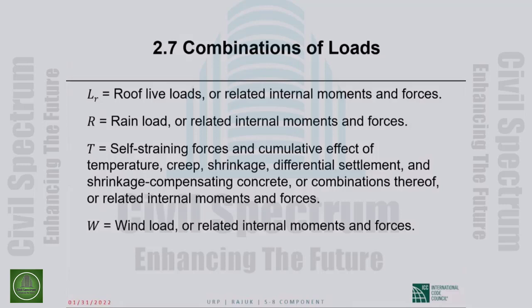Restrained volume changes. Okay, volume change may be because of temperature rise or fall, or volume change may be because of shrinkage. Water, as water evaporates out of the concrete, it shrinks.